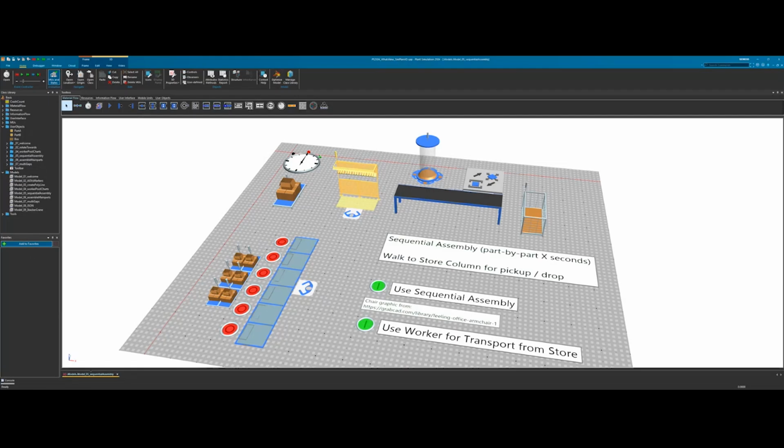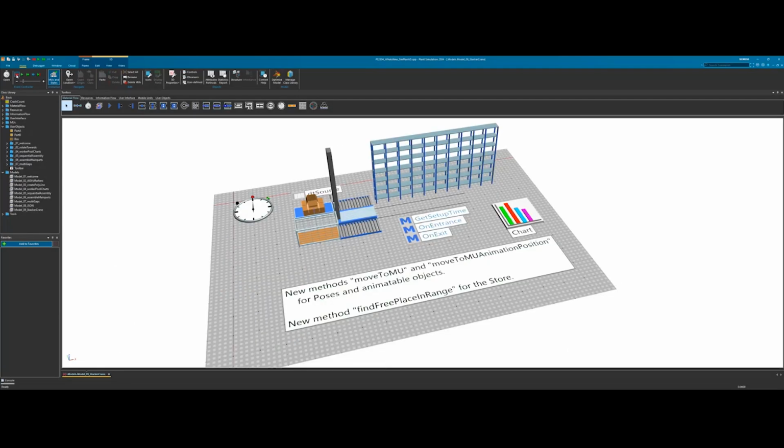Steve asked, is this crane standard in PlantSim version 25? It has a lift table but no fork. I don't exactly know what you mean with standard. If you're referring to the last model that I showed you, obviously this is not standard because I built it myself. I assume this question came up before I explained that this is a single proc object with custom 3D graphics.